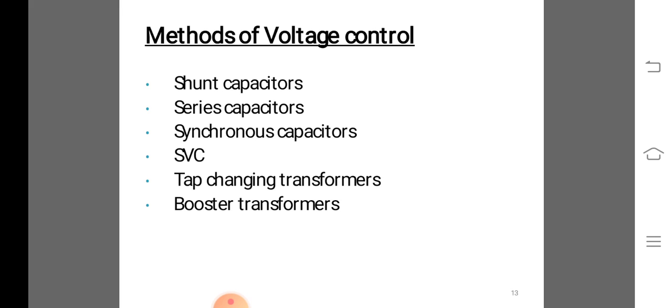Even though the capacitor and reactor are connected to the low voltage side of a step-down transformer, the capacitor bank may be distributed between high and low voltage buses. The capacitor bank often includes in part a harmonic filter, which prevents the harmonic current from flowing in the transformer and the high voltage system. Filters for the fifth and seventh harmonics are generally provided.